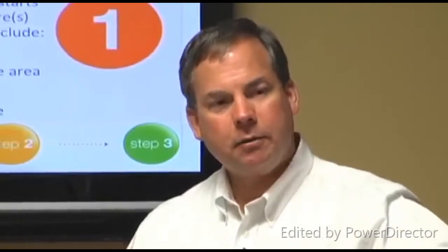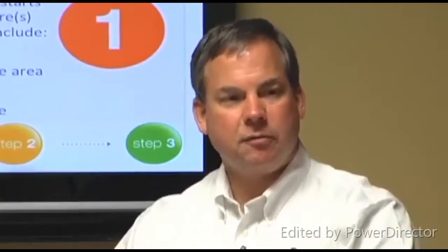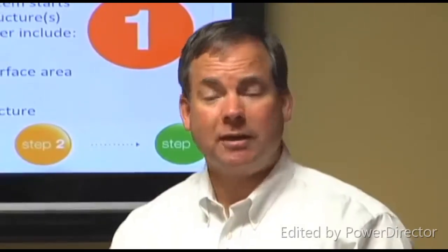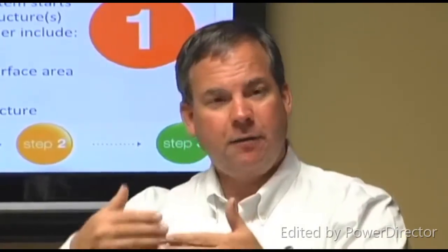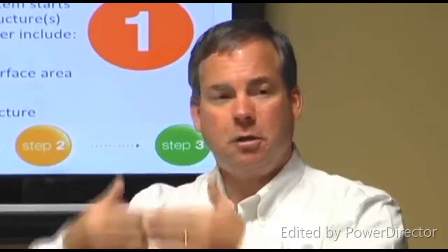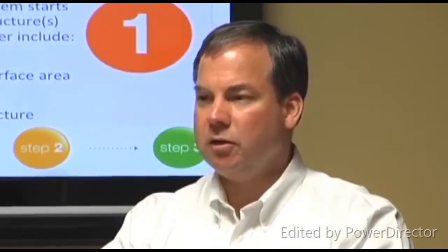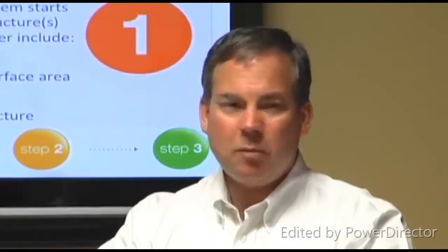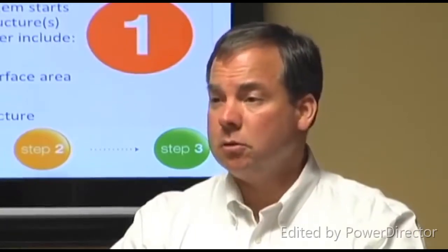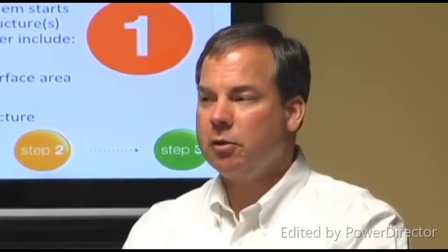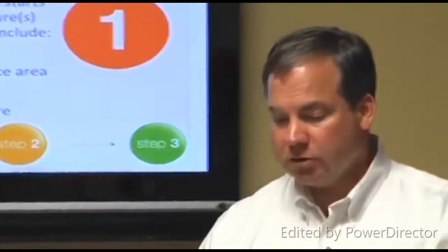You can test for continuity. Oh, you can. Yeah, you can go to one end of the pipeline, go to the other end of the pipeline, run a wire between them and see if there's electrical continuity or not. We will do continuity testing on some structures. That seawall I showed, those are generally individual segments of sheet that are piled, driven into the ground and connected. Well, you want to make sure those connections are electrical. So we'll actually go out and we'll test to make sure there's electrical continuity. There again, it's pretty easy to bond across them. So there's some issues there.